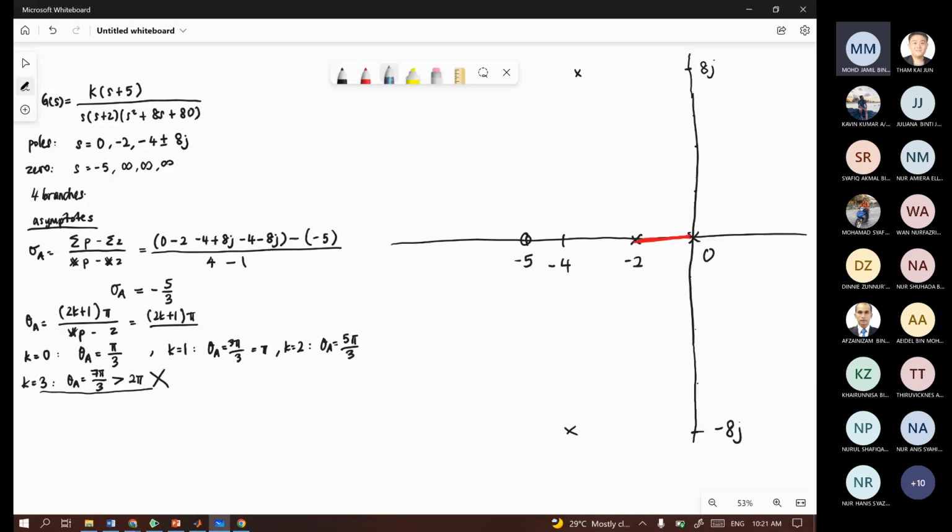And then from -4 to -5, second last. So we have four poles, an even amount. So again, there is no root locus on this region. And then lastly, from -5 to -infinity, we have five total of things, four poles and 1 zero. So we have an odd amount, then we have root locus here.